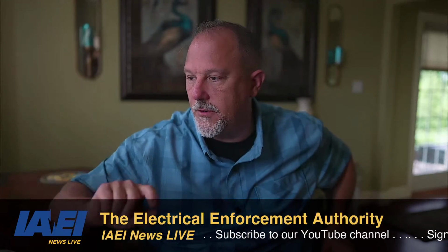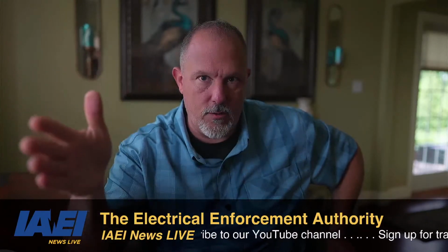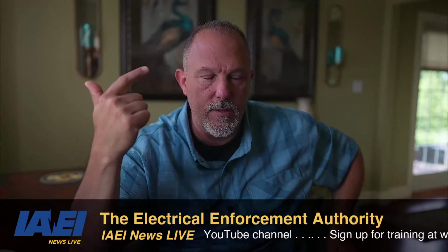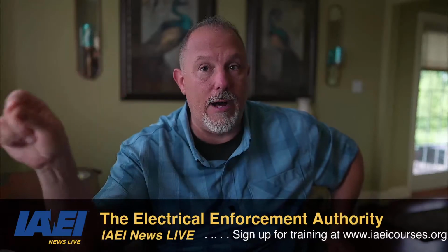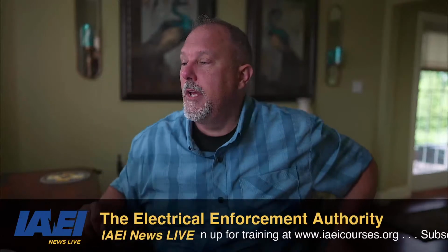Okay, so let's go down to 210.52. Now some key terminology is critical. You have to understand the definition of an outlet, receptacle, and dwelling unit. 210.52 applies to dwelling unit receptacle outlets, not receptacles, receptacle outlets.